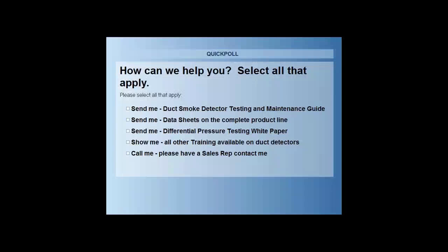Next question, just taking them in the order received here. How can we do a shutdown with an addressable duct detector? That question actually gets asked a lot because with the newer duct smoke detector models, it is different than how we used to do it.